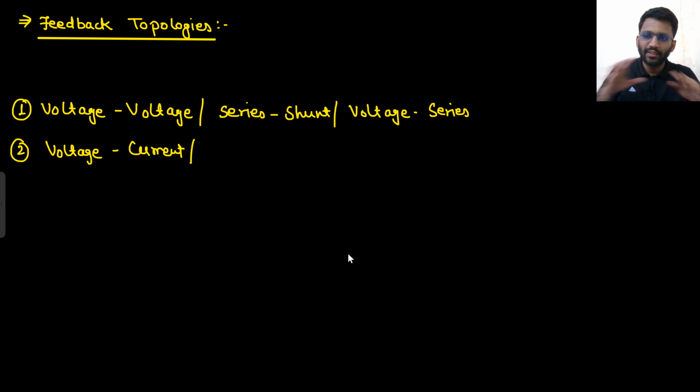Hi everyone. In this video we are going to study feedback topologies. What did we study in the previous lecture? At output there is always sampling, at input there is always mixing. Output will be sampled and mixed with the input. In shunt connection, voltage will be sampled and current will be mixed. In series connection, current will be sampled and voltage will be mixed. So this was the conclusion, the 3 points we studied in the previous lecture.